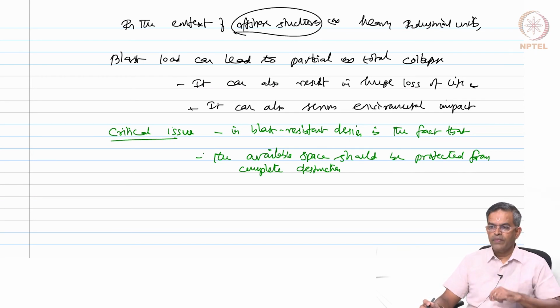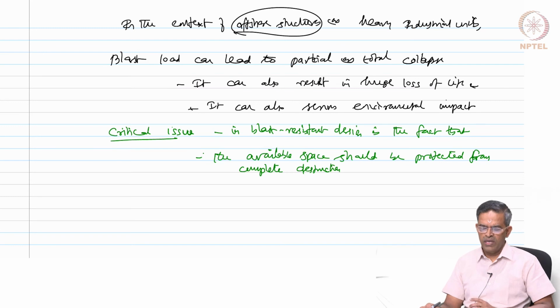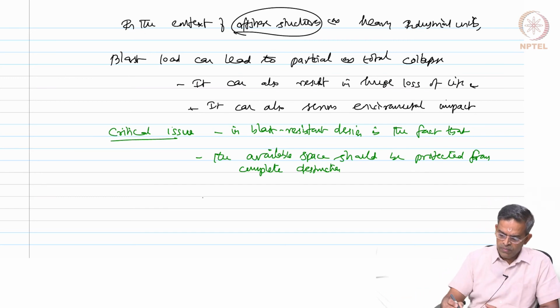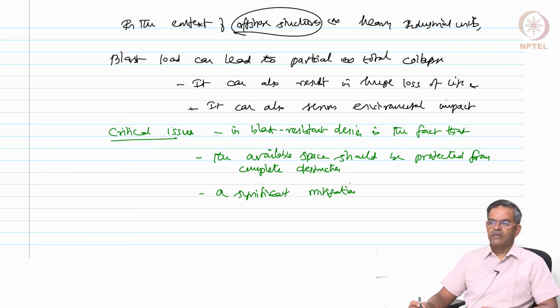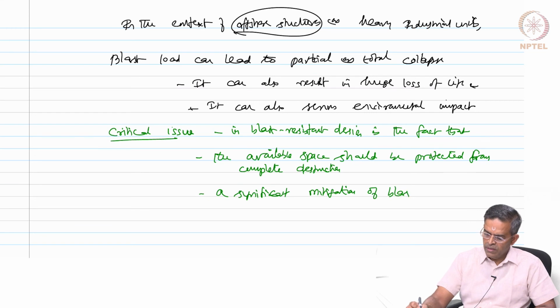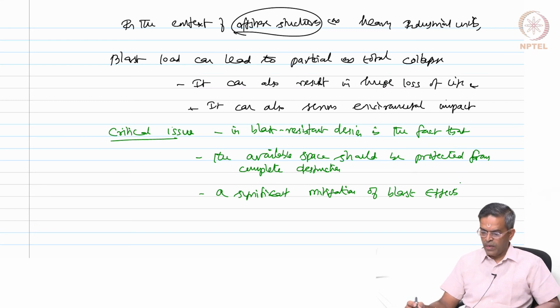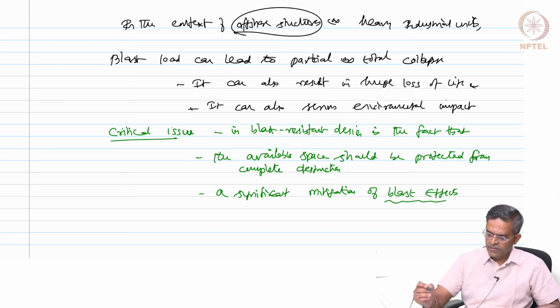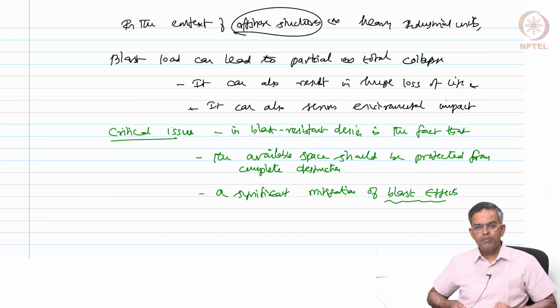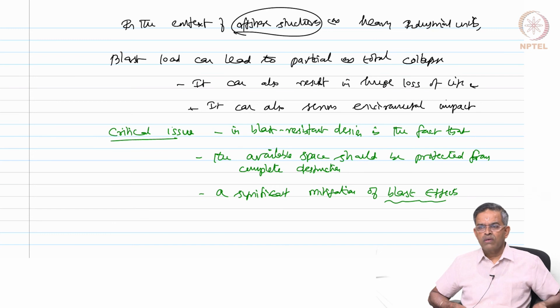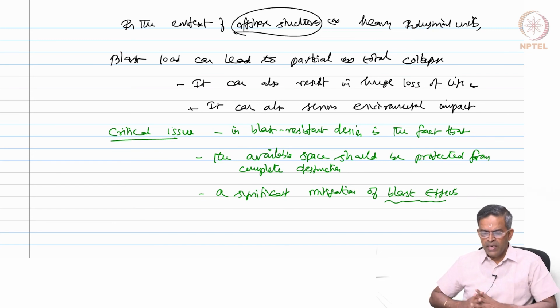Okay. Because available space in an offshore facility is very limited and very expensive. Therefore, we need to protect that space. So, we are here looking for a significant mitigation of blast effects. So, we are not looking for a complete blast proof concept, we are looking for blast effect mitigation in the design.